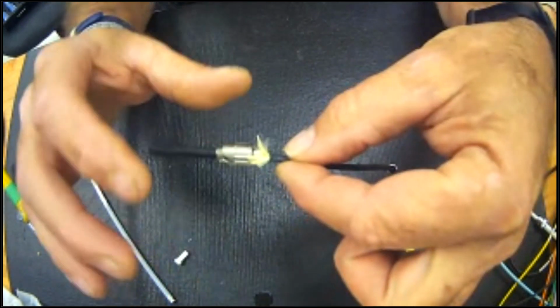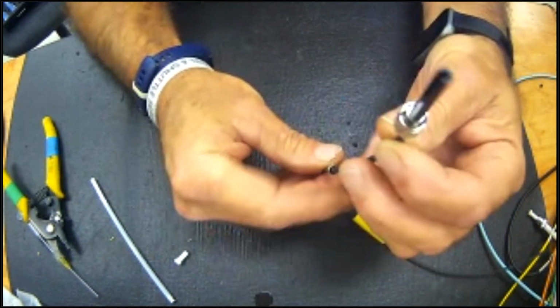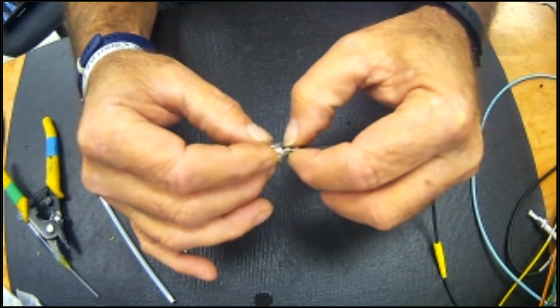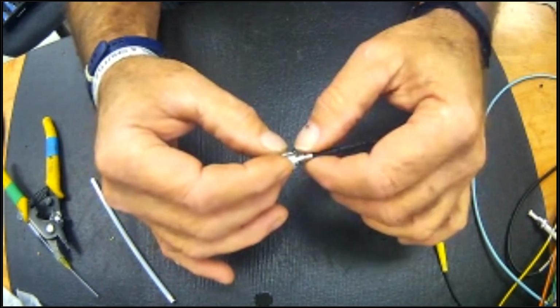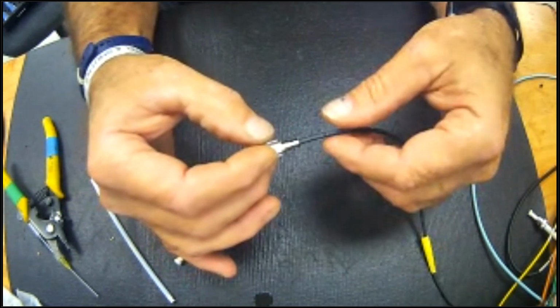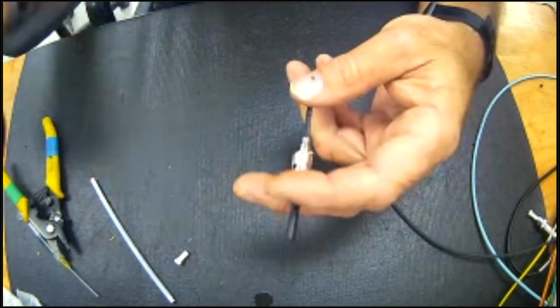Okay, so the yarn is basically our braid, and we're going to slide our stepped ferrule up to the butt of the connector, sliding it all the way up. Don't worry that you see a little excess of yarn. The boot will actually push that up inside with this particular brand. I'm fond of this manufacturer, Senko, by the way.